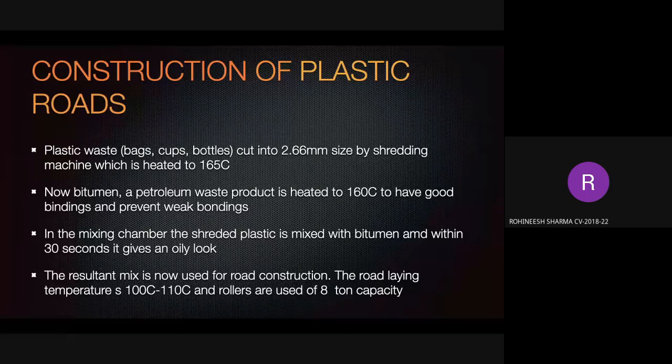In the mixing chamber, the shredded plastic is mixed with bitumen and within 30 seconds it gives an oily look. The resultant mix is now used for road construction. The road laying temperature should be 100 degrees Celsius to 110 degrees Celsius and rollers of 8-ton capacity are used.